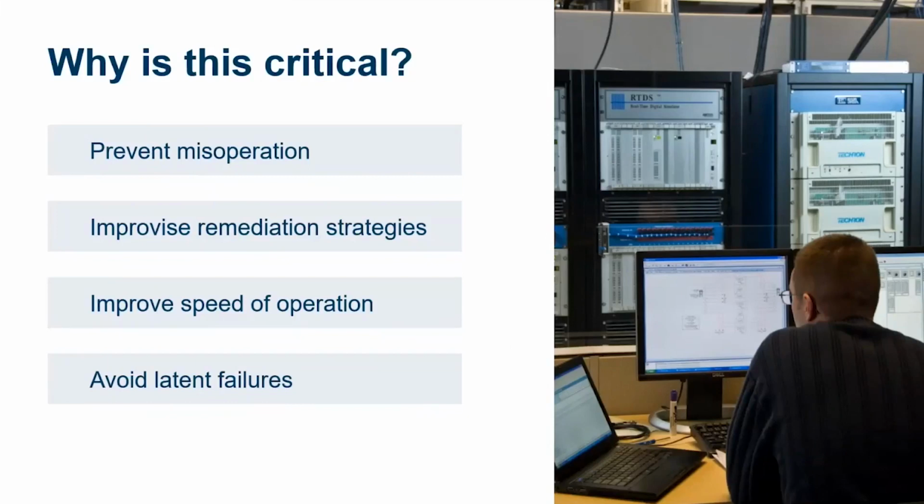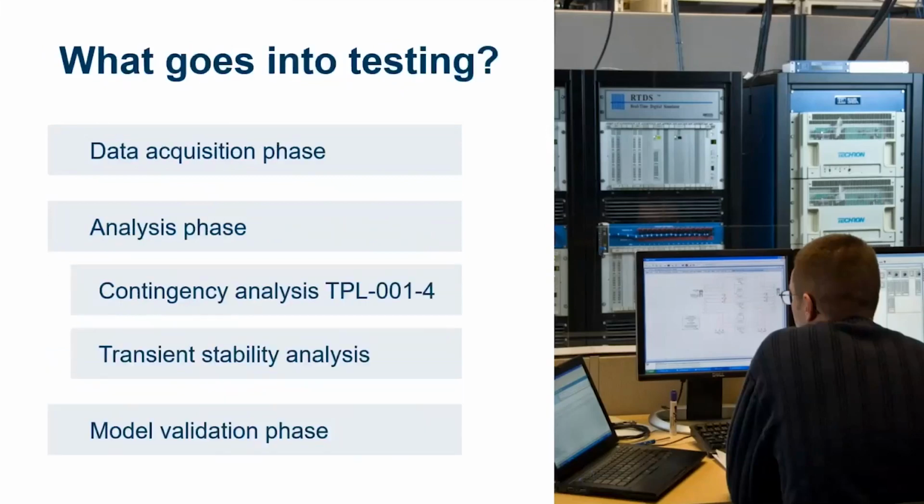Deterministic operation of the RAS is essential to the stability of the systems. Hence, meeting round-trip time requirements is critical. Latent failures are failures that happen over time. Such failures will also inhibit the RAS operation. Therefore, regular testing and maintenance is critical. A multi-layered approach is implemented during the development and testing phase of RAS schemes. Testing methods like automated batch testing, negative testing, scenario testing, etc. are performed to ensure every component of the RAS scheme is tested.